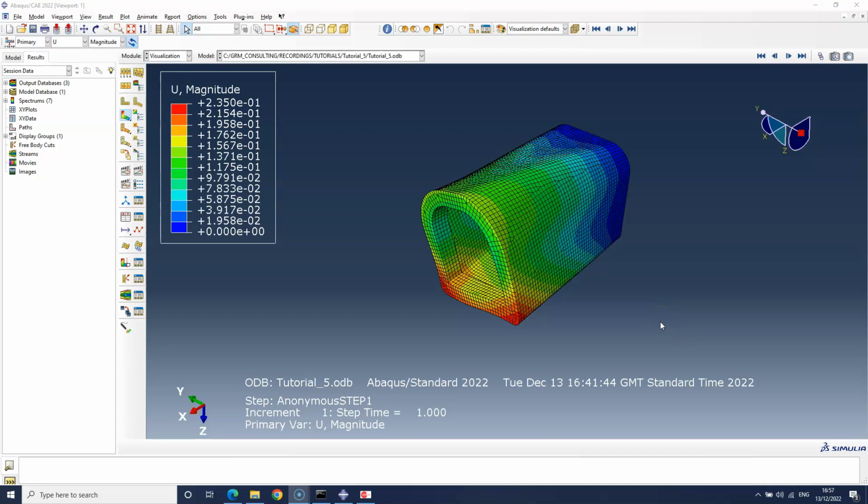For this example, we'll demonstrate the principle of linking opposing candidate plies located either side of a mirror plane. In this example, it will be the left hand side and the right hand side. Examples of 30-degree ply to then its minus 30-degree ply. This demonstrates symmetry, which we will prove with a subsequent CSV file made from the optimization.